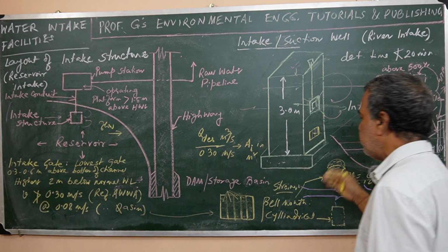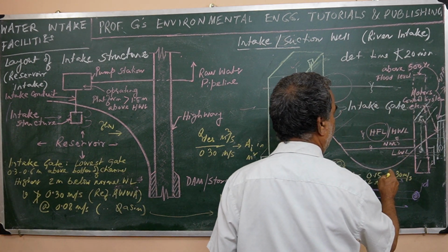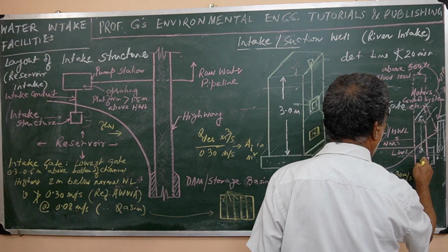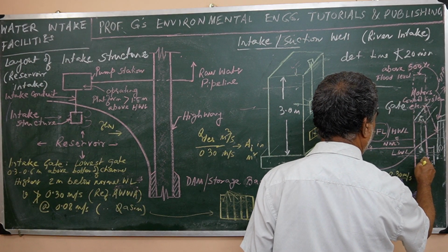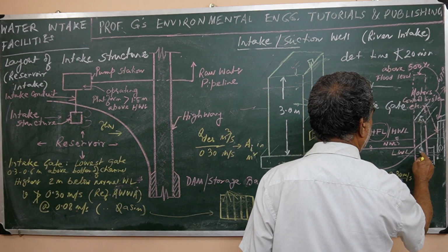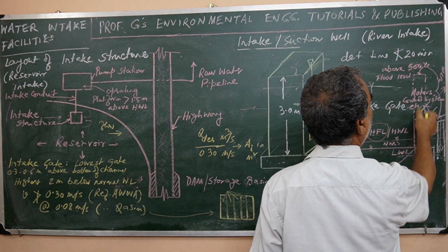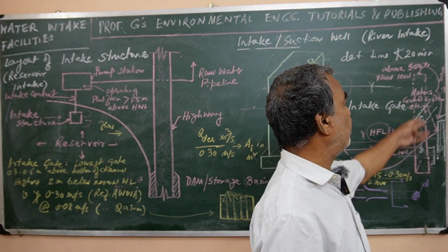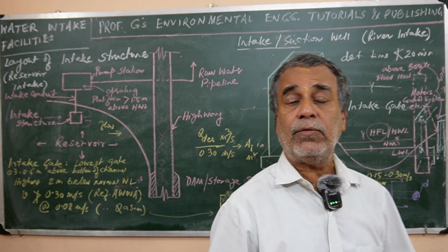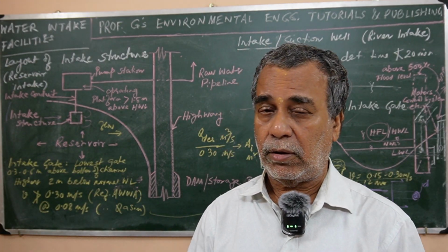Different strainers could be put so that before it enters the pumping system and the suction well, it is screened out, so that relatively clearer water can be pumped. Otherwise the pumping will be choked.